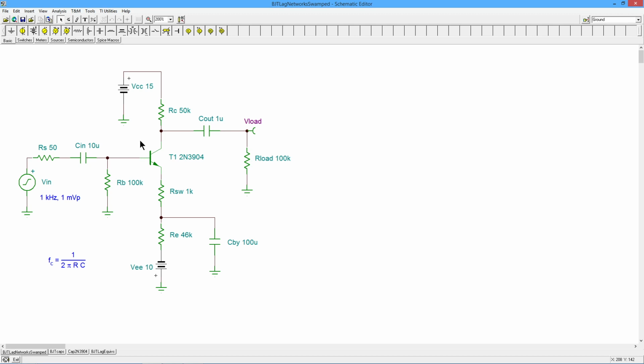And at lower frequencies, at audio frequencies, the capacitive reactances that are produced are big enough that we can ignore them. You push the frequencies higher and higher. Don't forget our handy-dandy frequency equation over here. As we go higher and higher and higher, that is no longer true. We can't ignore them. They start impacting the performance. Okay? All right, so how do I find these little capacitances?